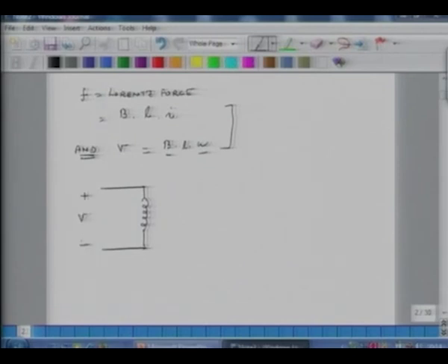So I have voltage being applied across this, there's a current going through this, and this voltage gets converted into velocity, and my current is getting converted into force, and the turn ratio, voltage equals BL times U. So my turn ratio is BL.